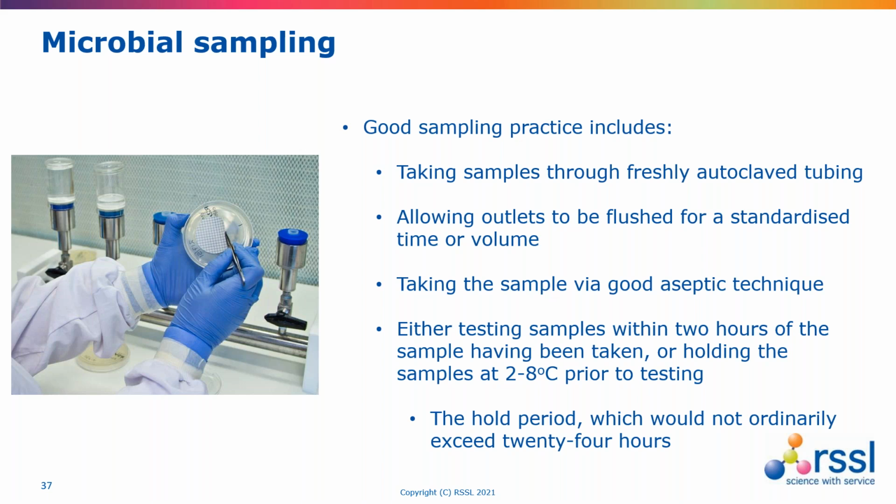Okay, so let's move on to microbial sampling. It's important that samples for microbial analysis are taken properly and that good aseptic practices are used. So samples are taken as production would use it, but in an aseptic manner. And also that we have some degree of qualification around the hold time. It will be typical, and it's actually drawn from UK drinking water testing standards, that samples are tested within 2 hours or they're held at 2 to 8 degrees for no more than 24 hours.